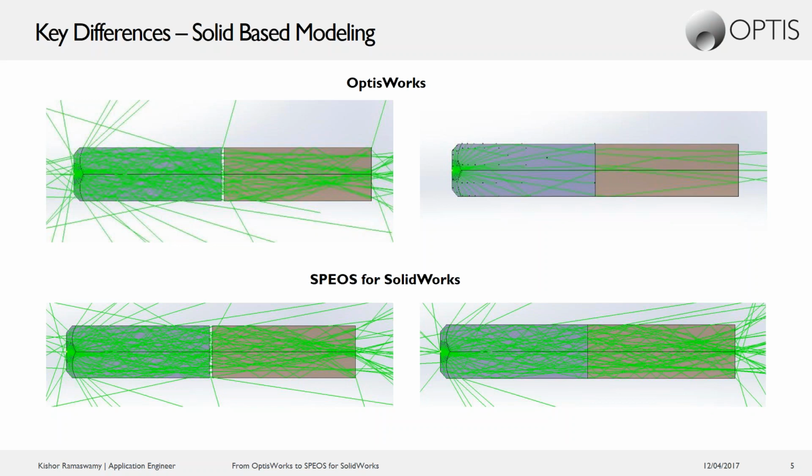But as soon as this air gap is removed, so as soon as the two bodies were tangent to each other, several errors were introduced into the simulation, as indicated by all of the X's that you see in the right image. So typically, the process on the left is actually what was done, where bodies that were in reality tangent to each other were modeled with a small air gap between them.